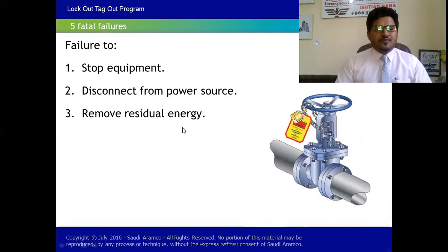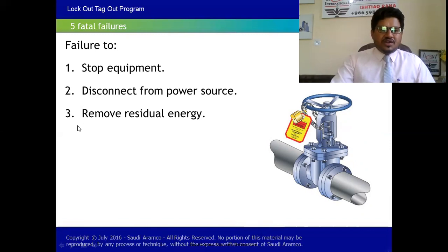No, it would be harmful, because consider if you're doing some hot work activities in a big oil storage tank and you thought a small amount of oil will not create any issue while you are welding. Then you truly need to understand the scientific reasons of isolation and lockout tagout.